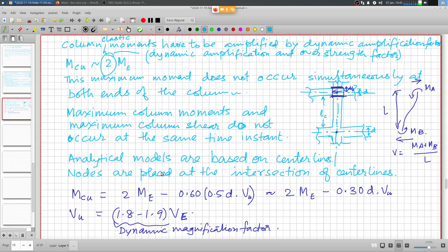We cannot curtail more than 50% of the reinforcement at the same place, so it has to be staggered, and of course it has to be avoided in the plastic hinge region wherever a plastic hinge comes up in the frame, in the column or beam.